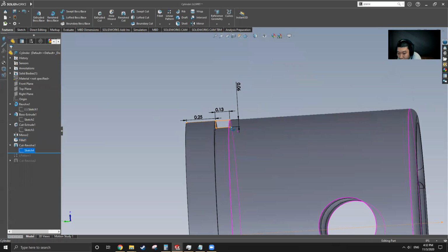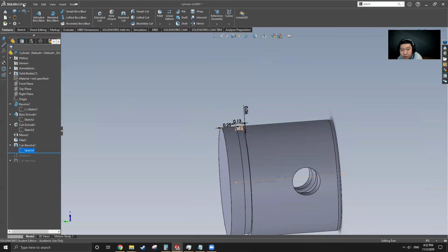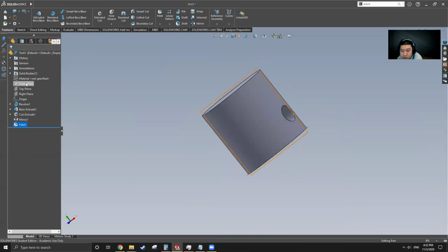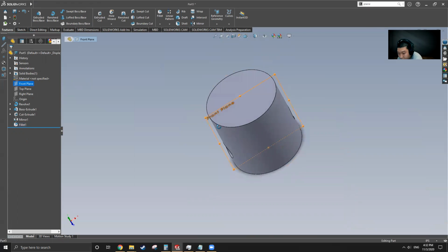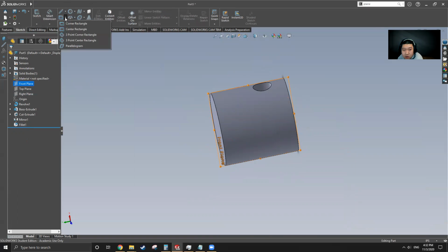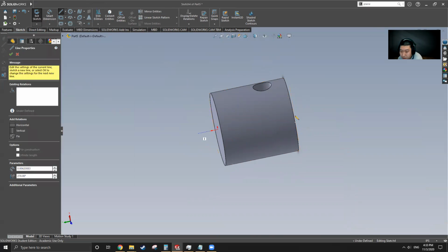We need to start making little rectangles. And the dimension of the rectangles is 0.06 by 0.13 and a quarter from the edge. And we cut revolve it. Okay, so actually the front plane can work as well because that's a cross-section plane, right? The right plane and the front plane, either one. And let's sketch right here and start making rectangles. Actually, start making center lines because we need a center line to revolve with, right?